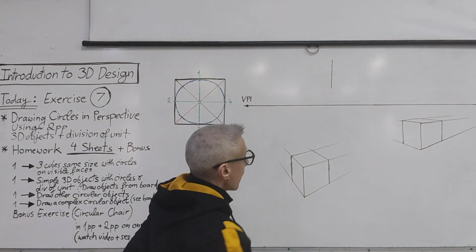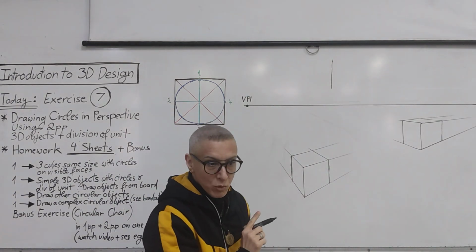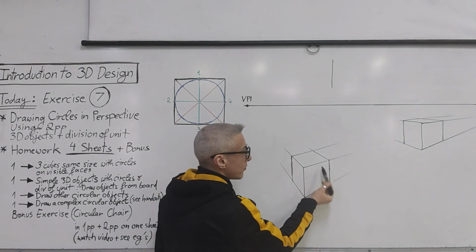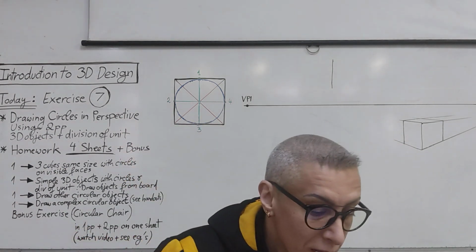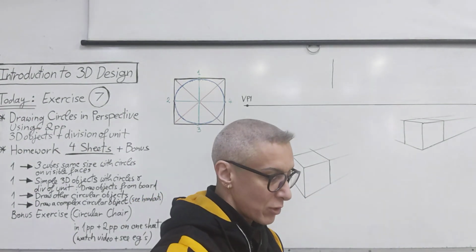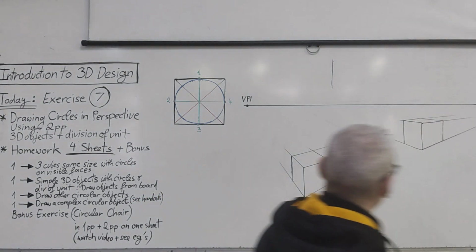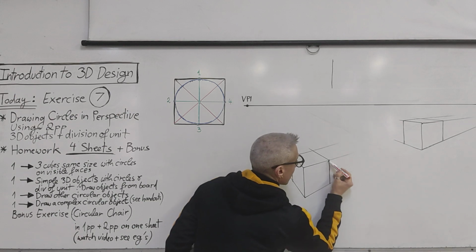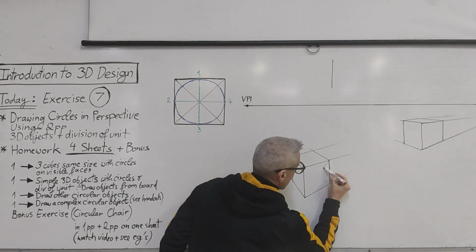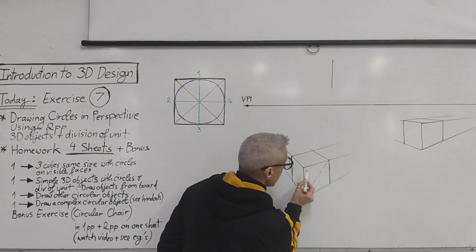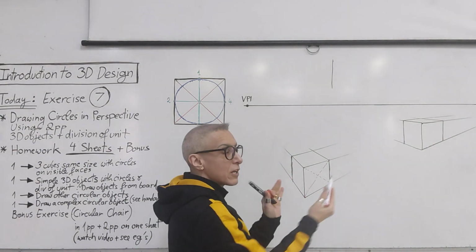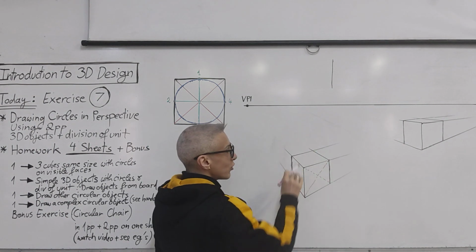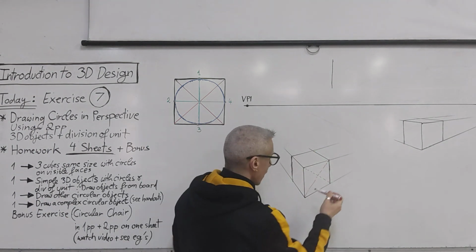The same, okay? Now, we have to put circles on all the visible faces. This is a visible face, visible face, visible face. The ones that are hidden, we will not put anything on them. So, how do we put circles? Diagonal, from here to here. Notice how each of the circles will be tilted differently and look different depending on its location.